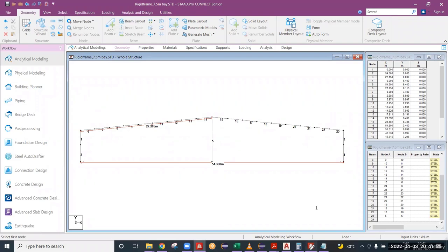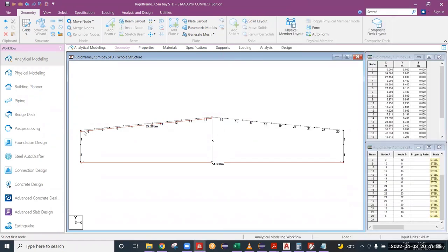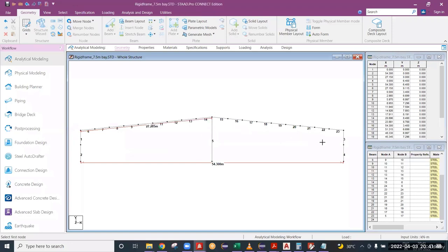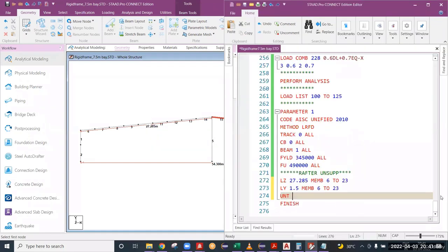But in our design, we cannot change everything like that. There will not be much effect like that. That's why we are giving the maximum value. But practically, the purlins will come closer here and you can keep constant spacing for this portion. Whatever spacing we have provided, only that spacing we have to take as Ly, right? What is the maximum purlin spacing you are providing on top of the rafter? That is what you have to take in the design. Okay. Clear?